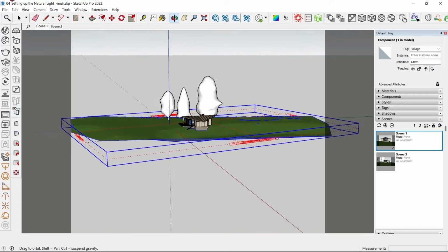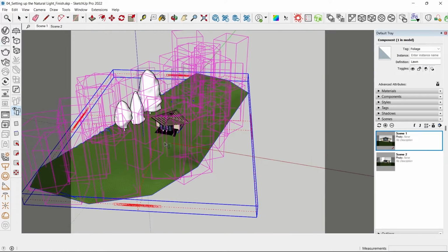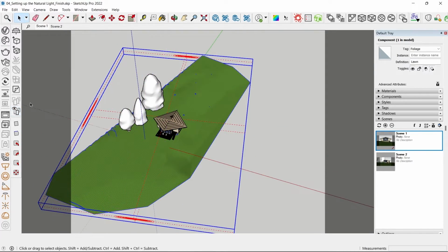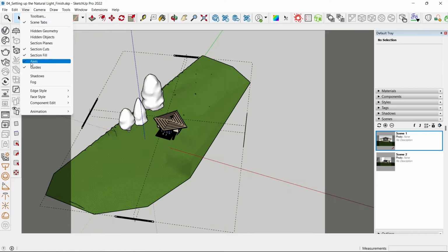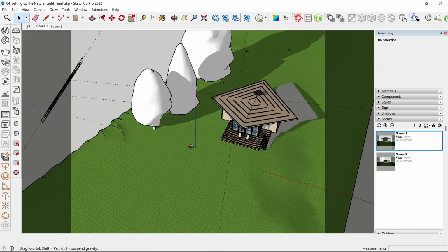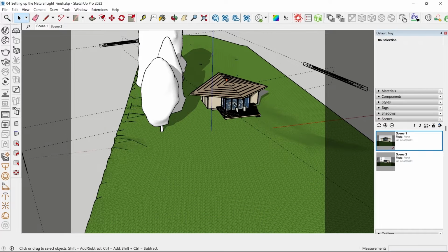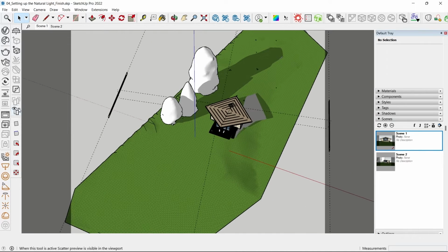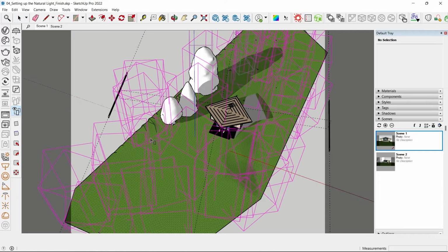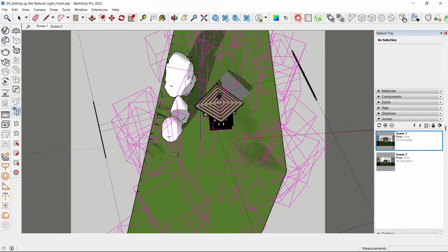So it's also important to understand the angle of the shadows. So let me just switch this off for a bit and switch on the shadows. So view shadows. So you can either change the shadow angle to make sure that the light is falling on the house. Now you can't really switch on the scatter viewer and then see the shadow of the trees because it's not generated the tree on the object. It's generated it as a proxy viewer which opens only in your V-Ray Interactive.